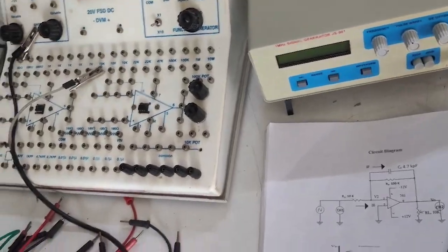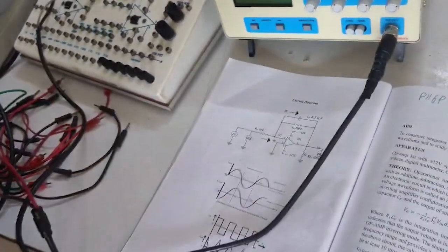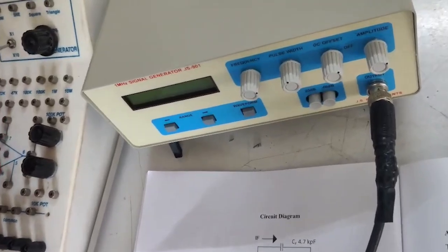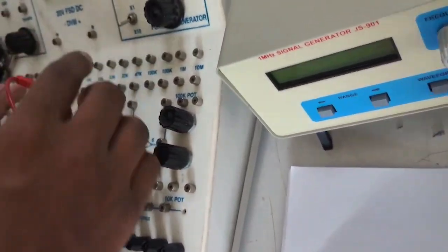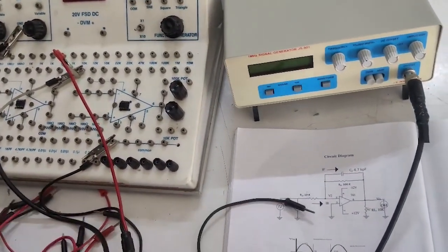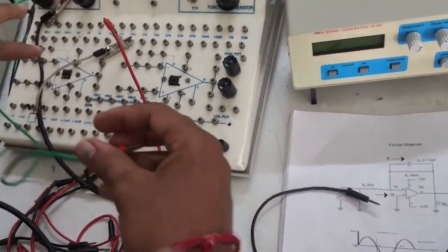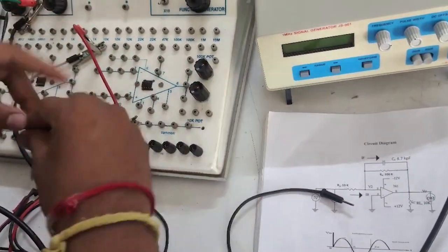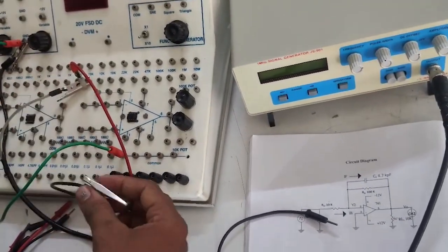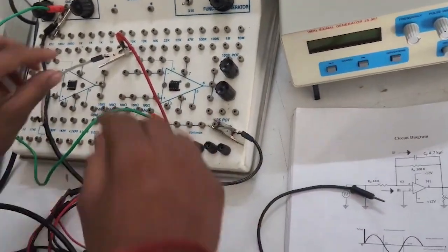Now we're going to take channel 1, the audio oscillator channel 1, and connect the positive end of this to the same point as your audio oscillator here, and you're going to ground it to a common. Where you have connected the ground of the audio oscillator, from that point you just take this to the common over here. So basically all these points are now grounded, so you can connect any ground points over here. So this is grounded now.